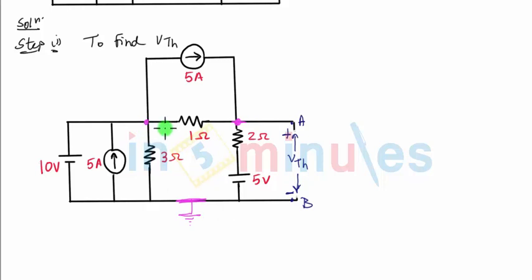So once I take these 3 nodes, out of which one is the reference node, all I have to do is apply KCL equations at these 2 particular nodes. So let me call this node voltages as Vx and Vy. And later on, you can see that my Vy is the voltage at this point, which is also point A, because there is nothing connected between point A and this node Vy. So voltage Vy is the voltage at this node with respect to ground.